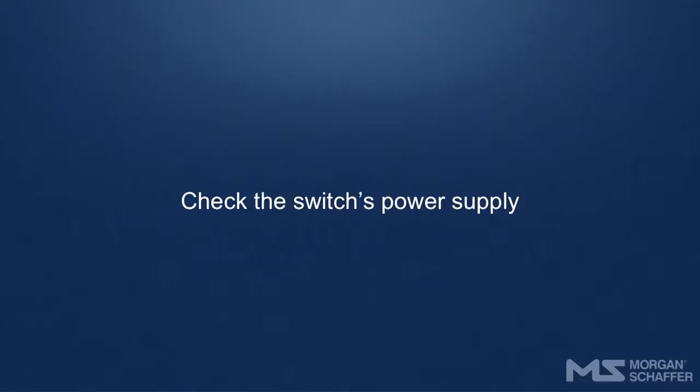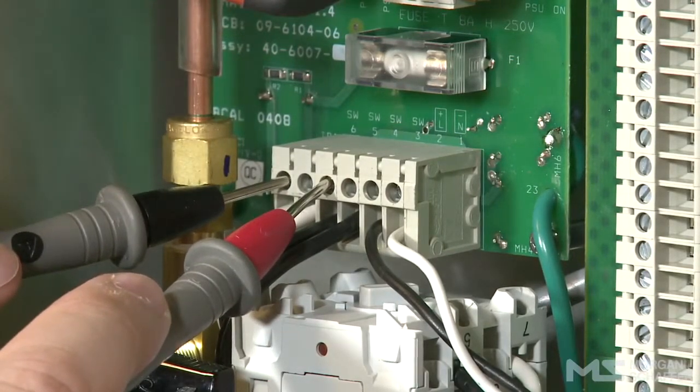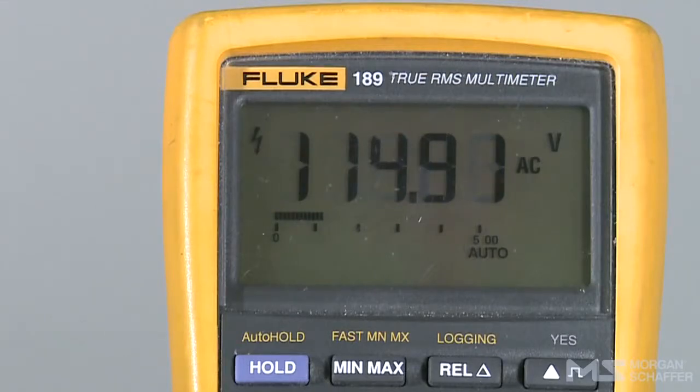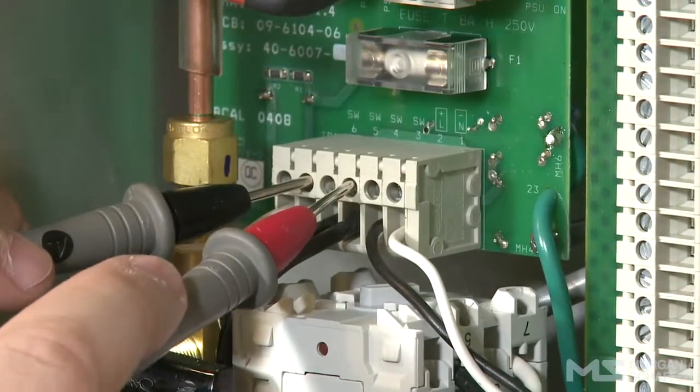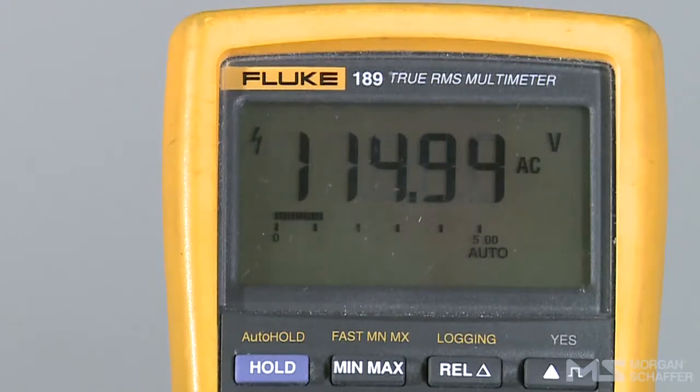Check the switch's power supply. Connect a multimeter between pins 6 and 4 of the TB1 connector. The voltage must be between 100 and 240 volts alternating current, or 100 and 220 volts direct current. Connect a multimeter between pins 5 and 3 of the TB1 connector. The voltage must be between 100 and 240 volts alternating current, or 100 and 220 volts direct current. If this is not the case, the switch must be replaced.